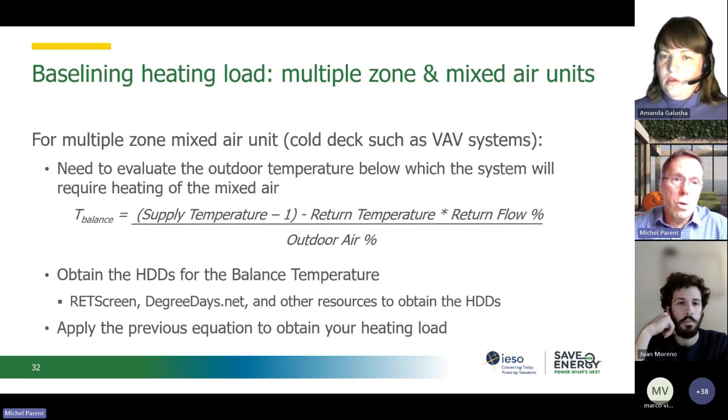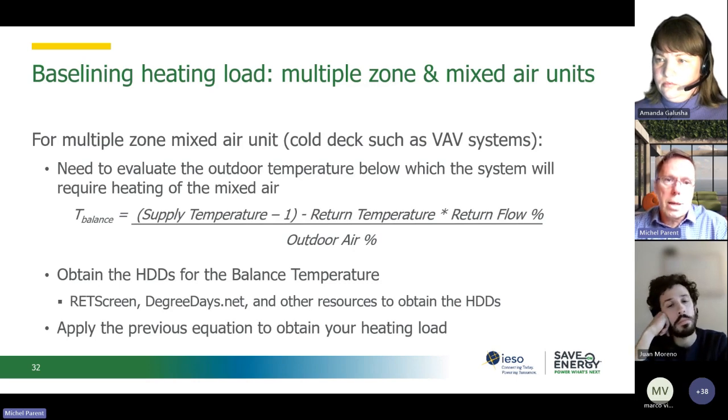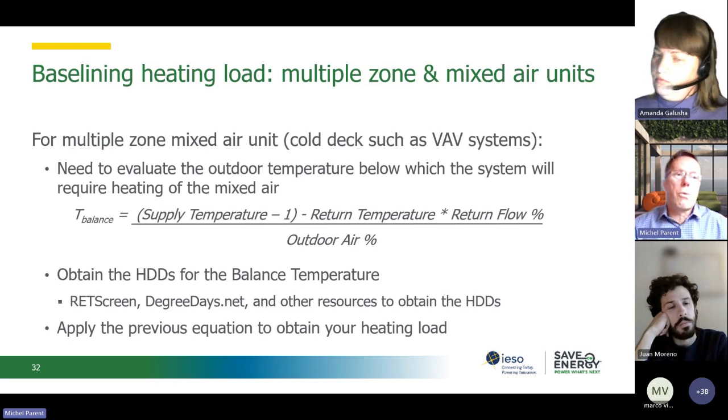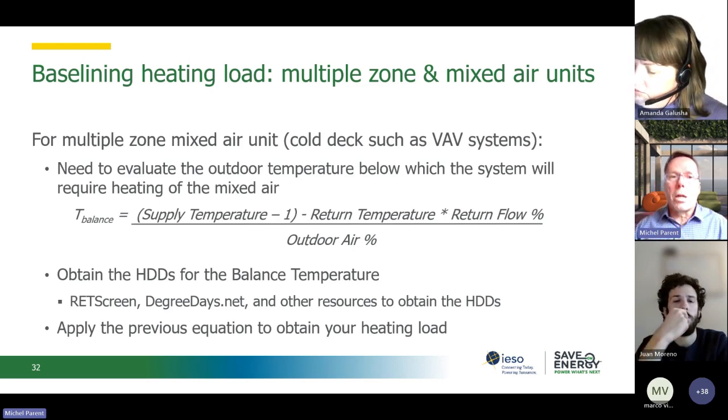So the quick formula here is you take the supply temperature minus the return temperature times the return flow divided by the percentage of outside air. So that was return flow in percentage. And that will give you your balance temperature at which you will evaluate your heating degree days.